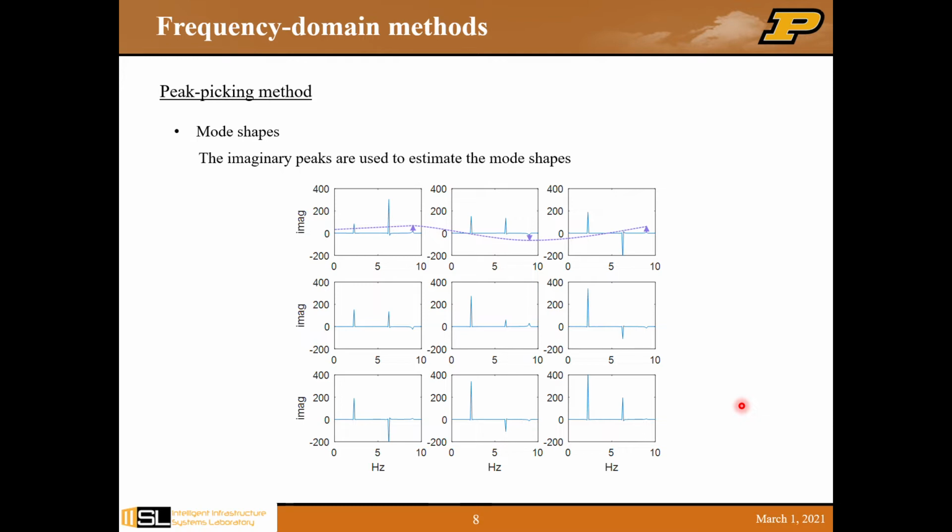It is actually easy to visualize, but not quite accurate because it mainly depends on the peak values without utilizing other information in the other frequency domain signals. Okay, and in most cases, it may not be easy to identify the natural frequency because of the frequency resolution.